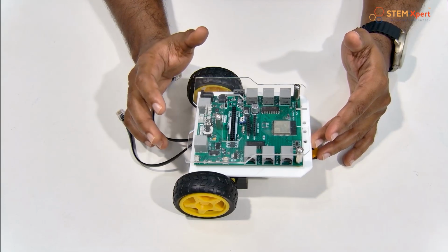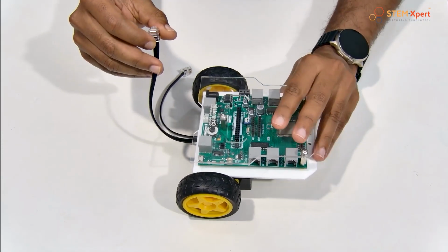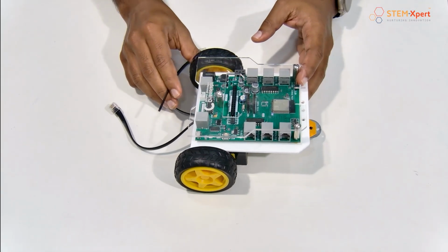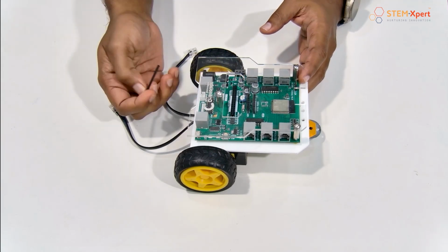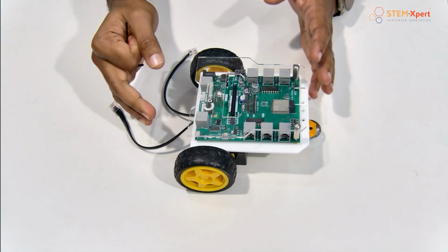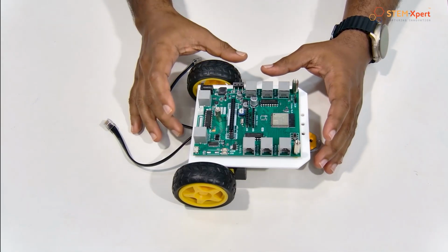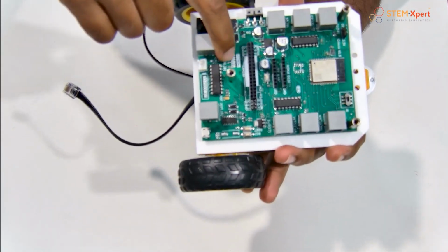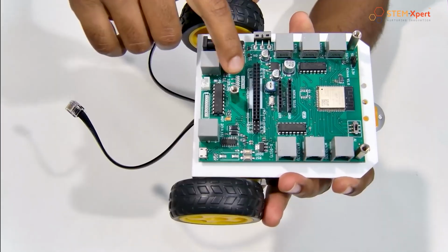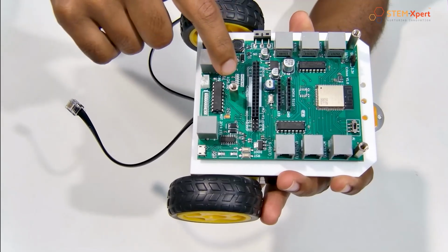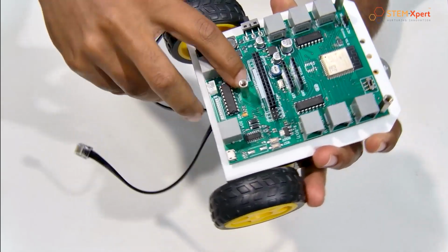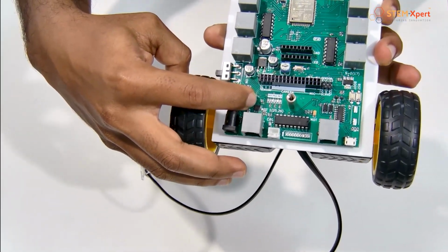Understood? Great. Now we are going to connect the motor RJ11 cables to these ports. First I will remove these 3 screws and show you the built-in LEDs available. Please let me remove this part. We have removed the top acrylic shield, and here you can see these are the LED pins. These are all connected to the motor pins, which are 25, 26, 19, 15, 32 and 33. These are the motor pins M1, M2, M3. You can see over there, right?